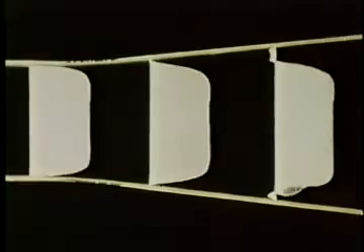The fluid, which was in the upstream boundary layer, is no longer in contact with the wall and is separated from it by a region of reversed or recirculating flow. The boundary layer is said to have separated. The point on the wall where the fluid in the upstream boundary layer meets the fluid from the region of flow reversal is called the separation point. The wall shear stress is zero there. Here, the point of separation of the laminar boundary layer is near the first wire.